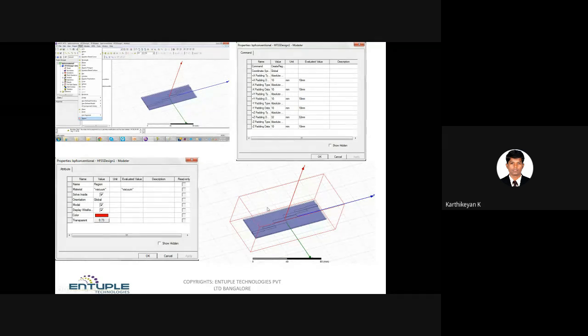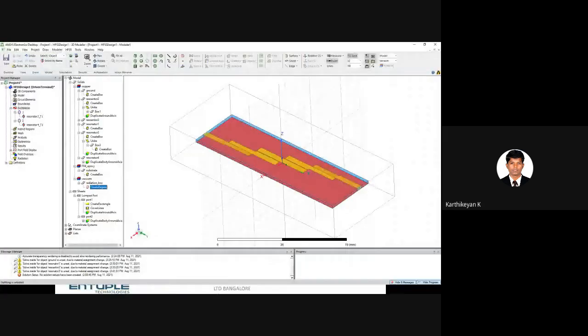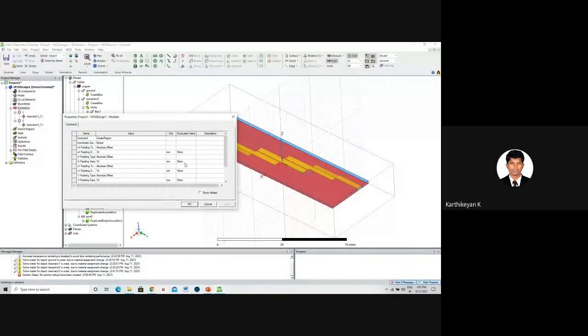If your antenna is omnidirectional or any other structure radiating in other directions, and you want to see and calculate the radiation in those directions accurately, then you can give lambda by 4 equally in all the directions. For now, I'm going to keep it only in this direction, the top Z, as lambda by 4. So click on Create Region and plus Z padding data. Plus Z padding data means in the plus Z direction how much radiation box size. I'm going to keep it as only 32 mm.